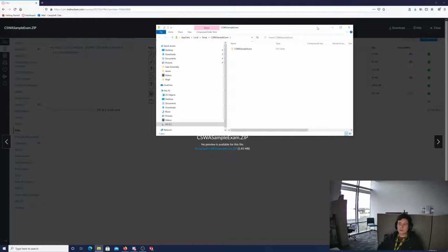Generally, with 3D printing, you want to use the biggest, flattest side as the bottom of your part, even if that means printing it upside down. So if you want to print a table with four legs, you're going to print it upside down. You're not going to start at the base of the legs. You're going to start with the tabletop, and then the legs are going to come up from there. Does that make sense?